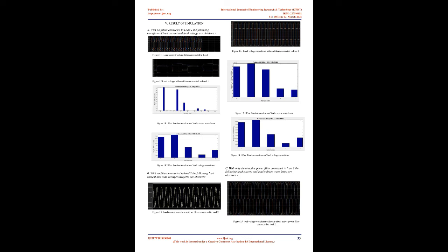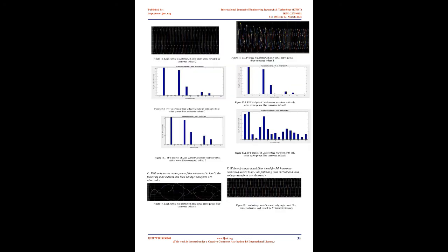3. 1980 Hz 3-level 3-phase VSC. The VSC converts the 500 VDC link voltage to 260 VAC and keeps unity power factor. The VSC control system uses two control loops. An external control loop which regulates DC link voltage to +/-250 V and an internal control loop which regulates Id and Iq grid currents, active and reactive current components. Id current reference is the output of the DC voltage external controller. Iq current reference is set to 0 in order to maintain unity power factor.